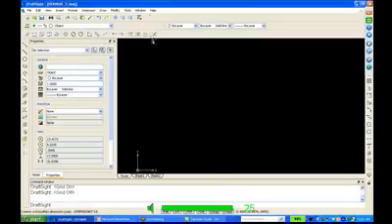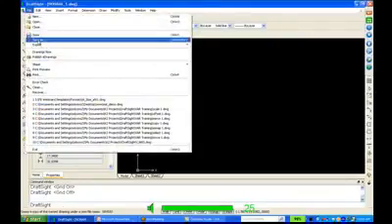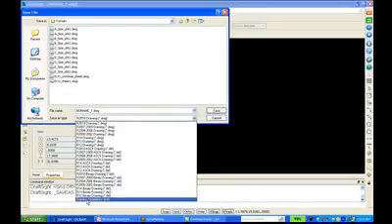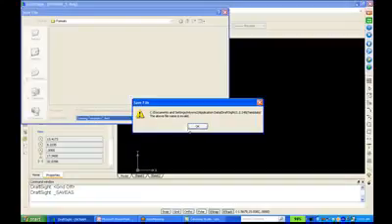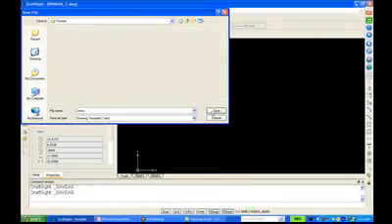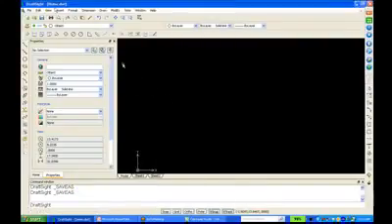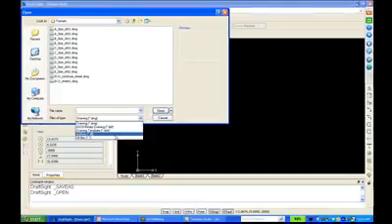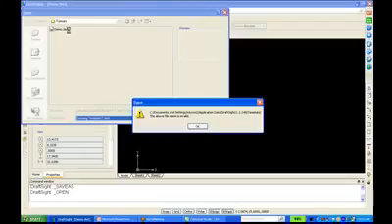Well, once I've done all this, what I need to do is save it. So when I go to File, I click Save As. Right here, it's asking me to save as a drawing. What I want to do is change it to template. So I click on Save As, Drawing Template, Demo. Let's call it a template file. And now I have a file called Demo Template. It's actually located in the folder that I'm working on right now.